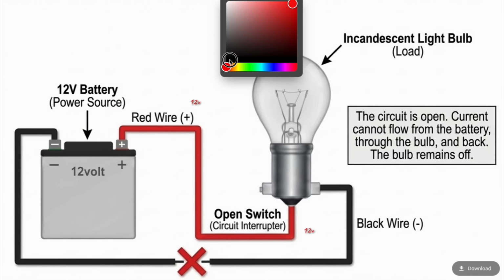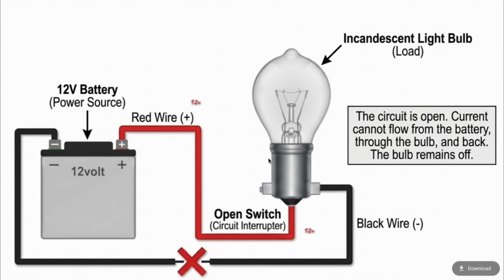Well, this is where it gets extremely interesting, and for many years as a young man, I never understood why I had 12 volts on the ground. Why have I got 12 volts on the ground? 12 volts. It's a bit off the page there, but never mind. And why have I got, after the break, 0 volts? 0 volts. And right at the battery, rightly so, 0 volts. That's our circuit, our faulty circuit.